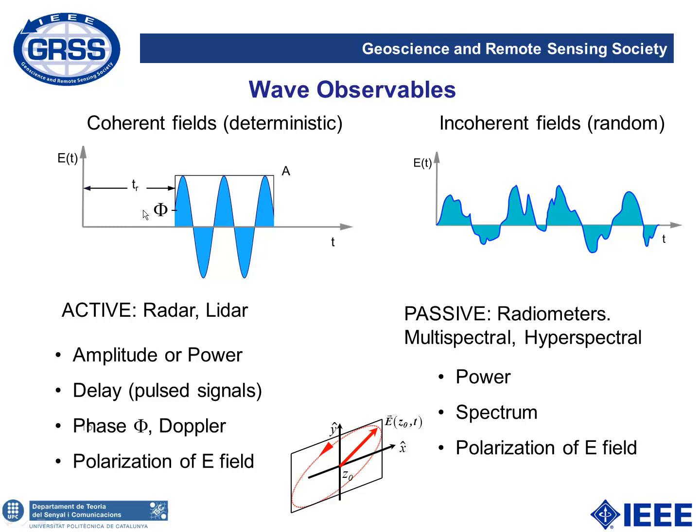Another parameter which is interesting in some applications is the phase. The phase is the angle at a point of reference, for example, the leading edge of the pulse or the center of the pulse. We can measure the phase, and this phase value here is indicating with extreme accuracy the delay and the path traveled by the wave.